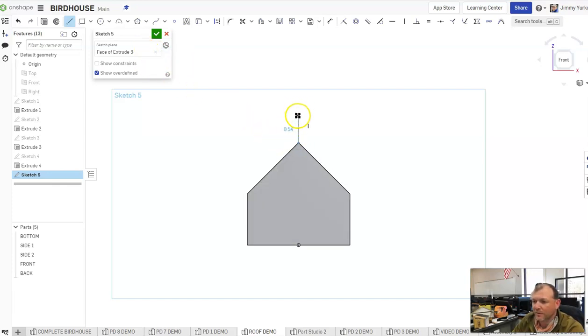I'm going to go vertical. I'm going to draw a vertical line. And then right now I'm just going to draw a couple more lines that are crooked. The only thing that I want to verify is that this line I created right here was vertical. So when I hover over it, you see the vertical symbol pop up. And whenever I hover over this dot, you see that pair of T-shaped constraints. Those are coincident constraints. So that means that all the dots there are coincident with each other. They occur at the same spot.